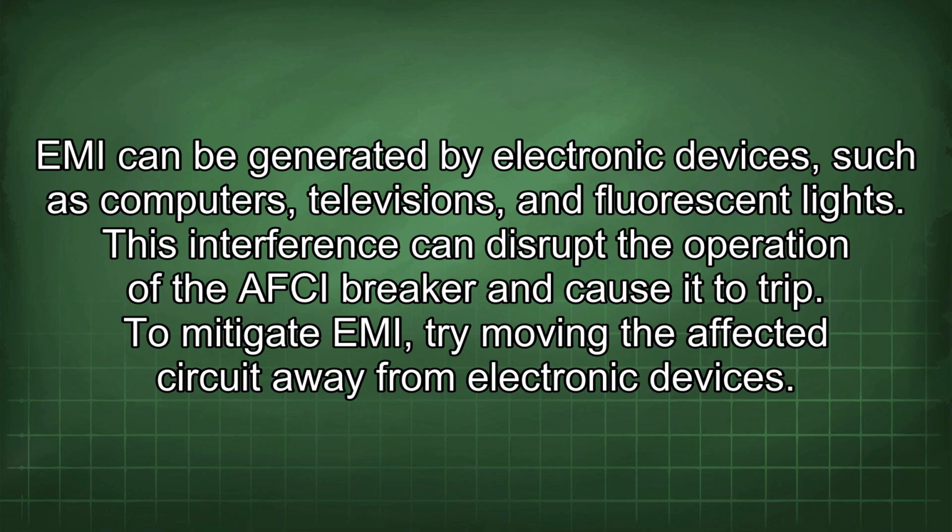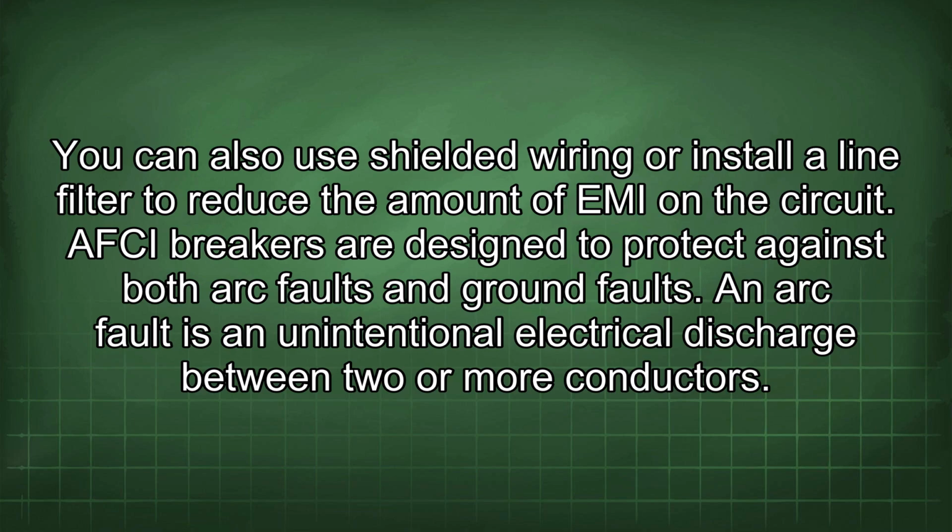To mitigate EMI, try moving the affected circuit away from electronic devices. You can also use shielded wiring or install a line filter to reduce the amount of EMI on the circuit.